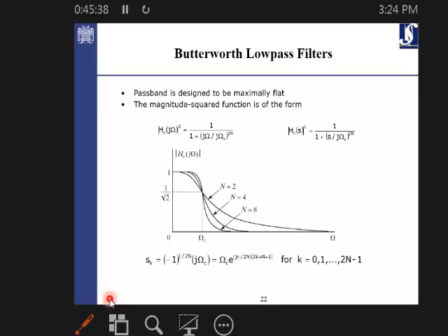That's the Butterworth. The Butterworth is also called maximally flat because, based on this, you see that here in the pass band, it's completely flat. There is no fluctuation, no oscillation. So if it's necessary for your project, for your application, not to have any oscillation in the passband. There are some applications where someone asks you, please design me a filter without any oscillation in the passband. If that's the requirement, then you can use the Butterworth.